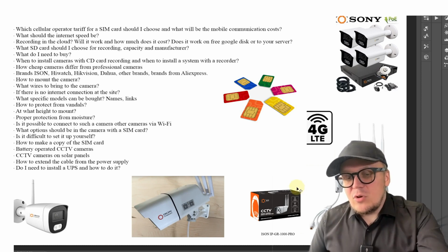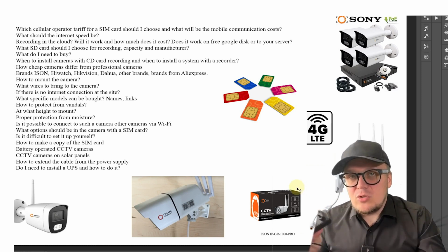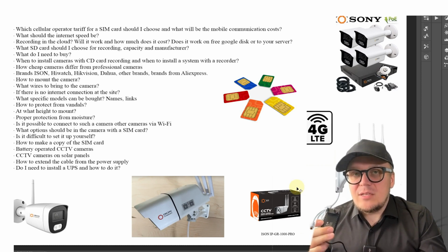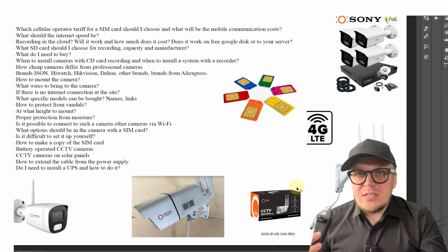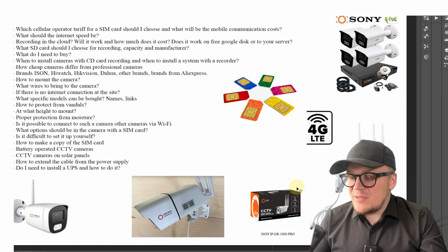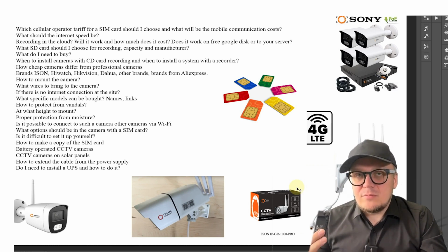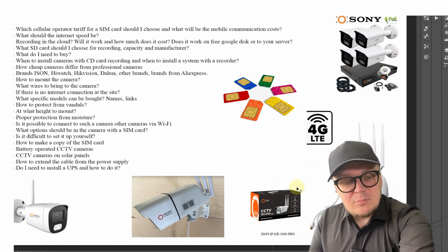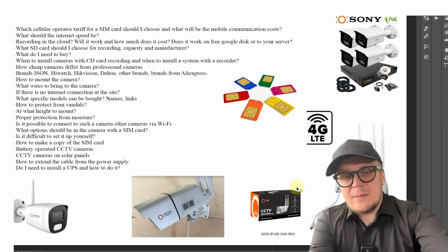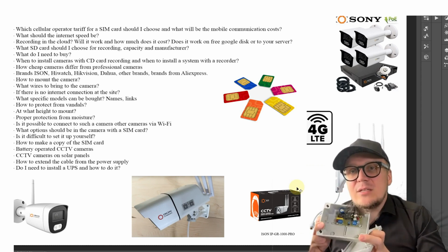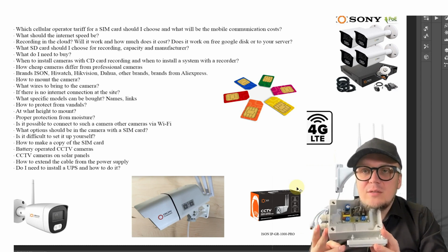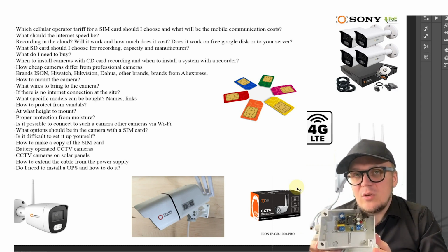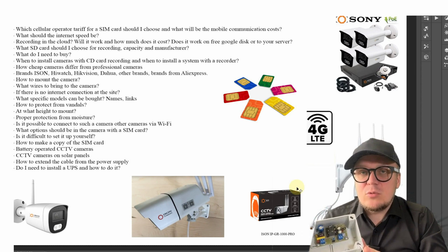And if I made an outdoor outlet, in any case, such a power supply should not be connected to an outdoor outlet. It is not waterproof and it will be unreliable. It will fail quite quickly within a few months, even if you just wrap it with something. In any case, if you are placing your camera's power supply outdoors, you will need a specialized outdoor power supply. It looks like this. It's a small box. On one side you connect the 220V wire here. We also have a separate review of this power supply. You can check it out on the channel for more details.